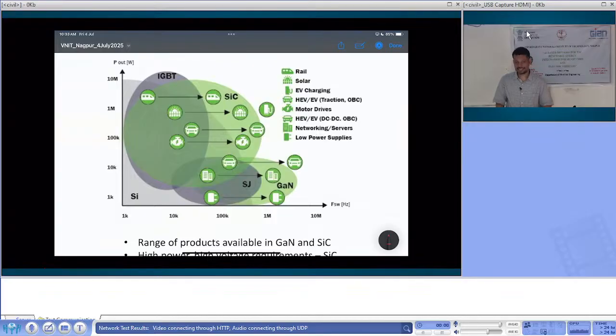Why is that the case? That's more of a device-related question, but what I understand by talking to some of my friends who are in this area is that we saw the vertical structure of MOSFET. In GaN, as of now, it's not possible to create the vertical structure. So it's still a lateral device, and a lateral device you cannot create for very high voltages.